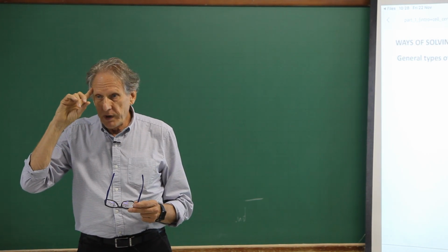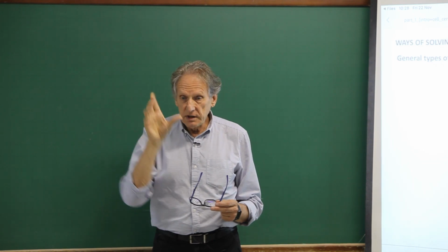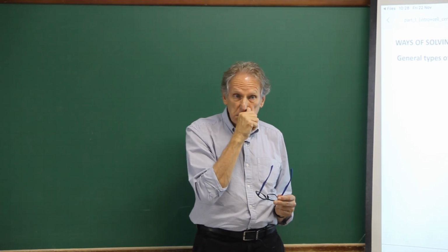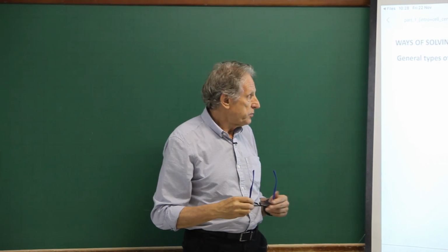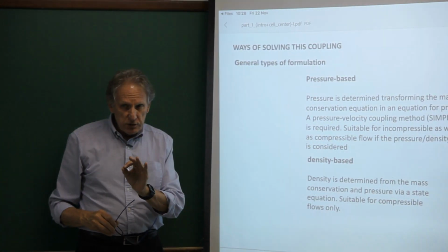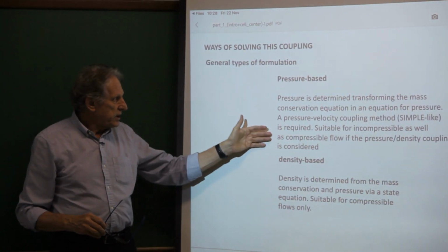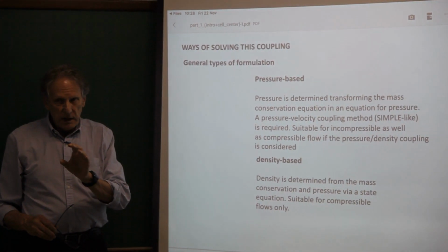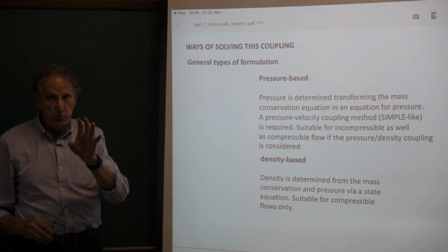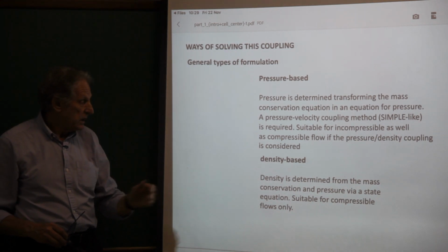It's still pressure-based because the continuity or mass conservation equation is transformed into an equation for pressure. So this is really important. I want you to keep in mind: pressure-based is not only suitable for incompressible flows, it's for both compressible and incompressible.